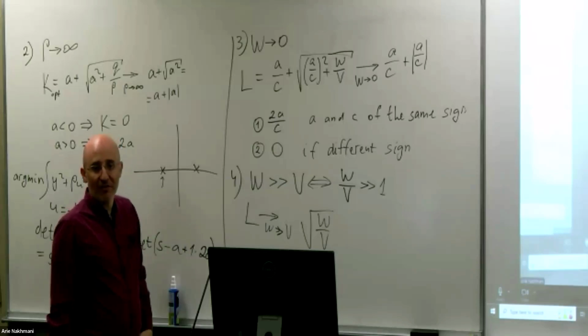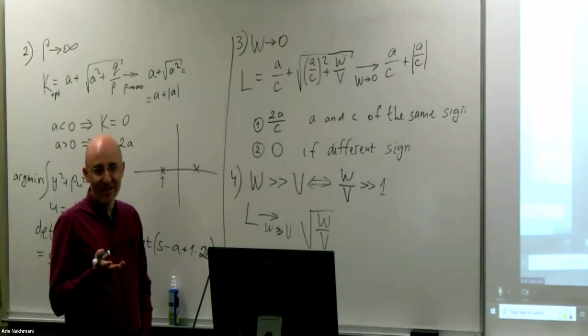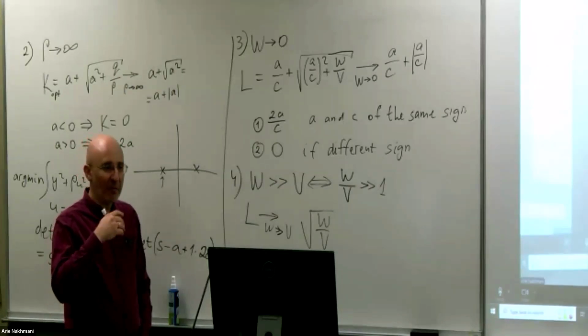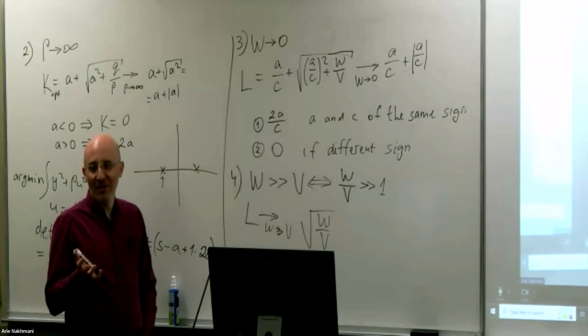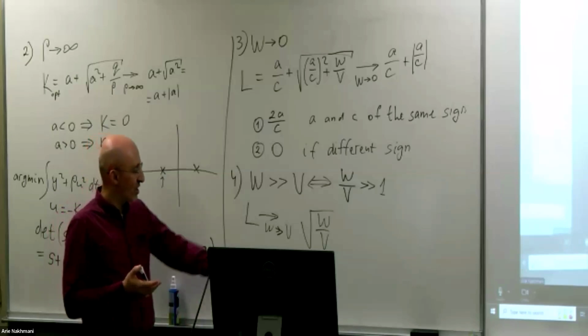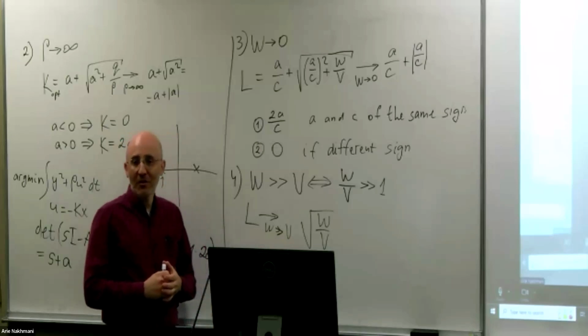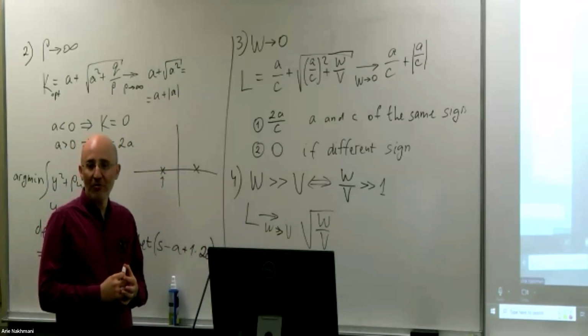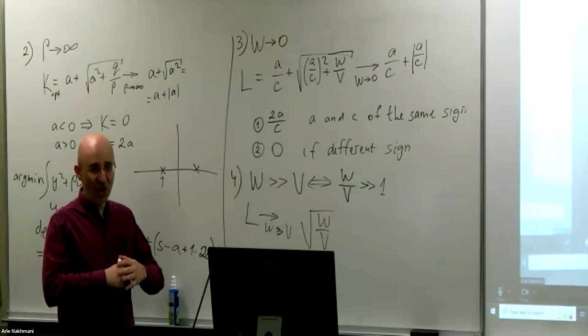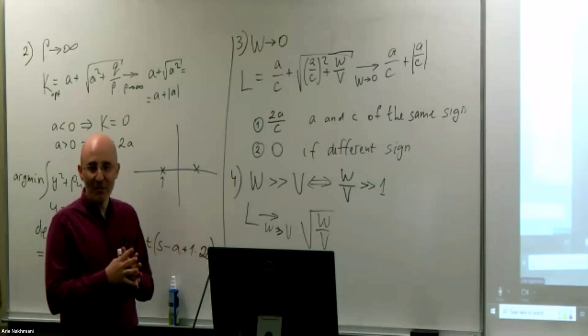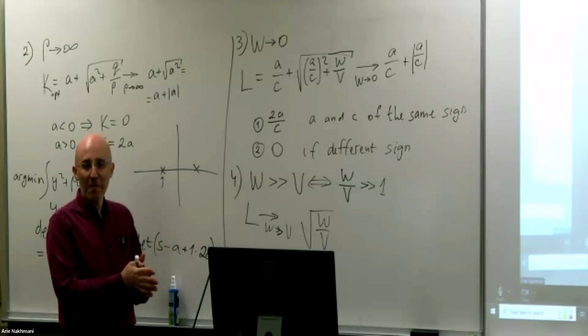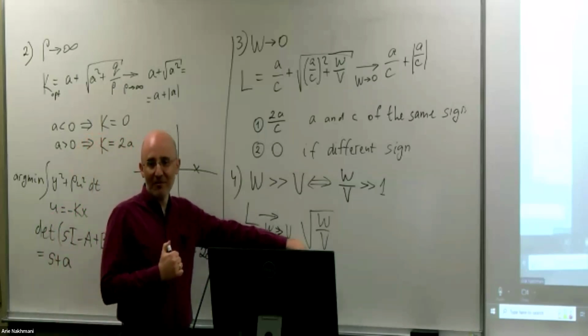Is it reasonable? Does it make sense? It makes sense because you want to penalize on huge error or potential error in Y. Your model is uncertain, right? So you do not trust your model. You have a pretty horrible prediction of where your state is. After you have that prediction, you're saying now I have a measurement, which is pretty good. But error is still huge. I need to change my state significantly, right? So the states need to change a lot from my present states because the error is huge, but the measurement is good. So you need a huge gain for that case.